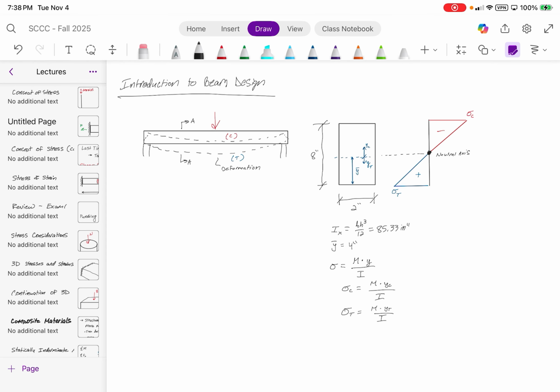What if bending was occurring about the Iy orientation? How would the beam look in that case? It would be rotated, where the 2-inch part would be basically the height of the beam. And then you would stand on top of it, so it would flex a lot more, right? Does that make sense? So I is just a general notation.